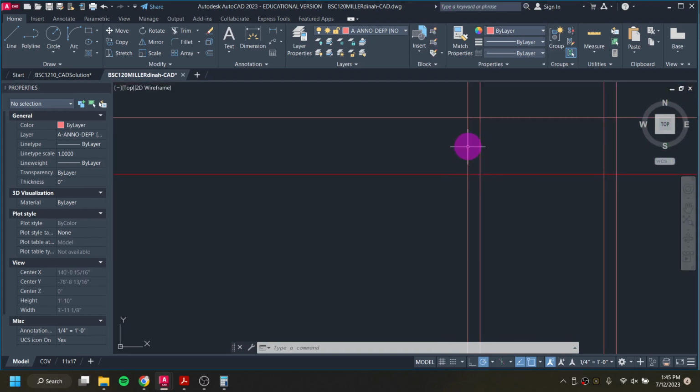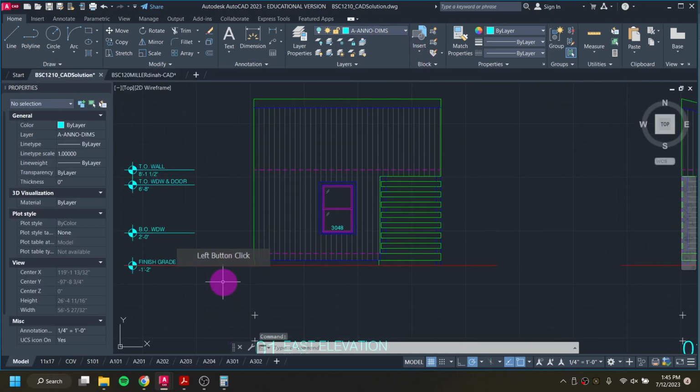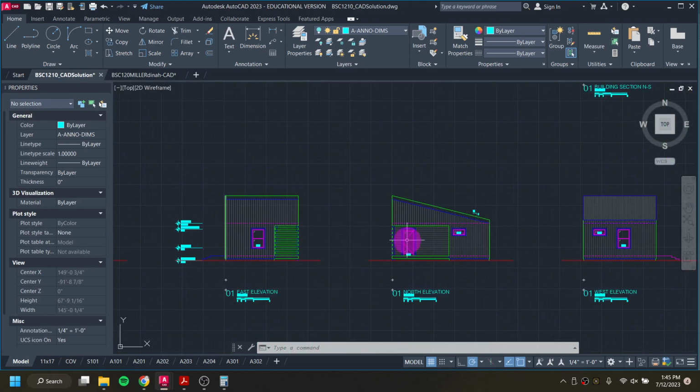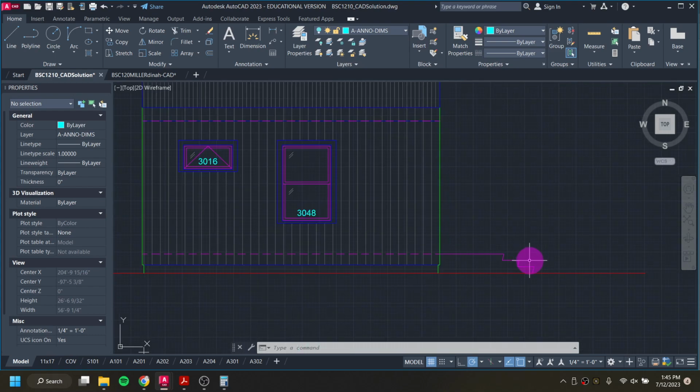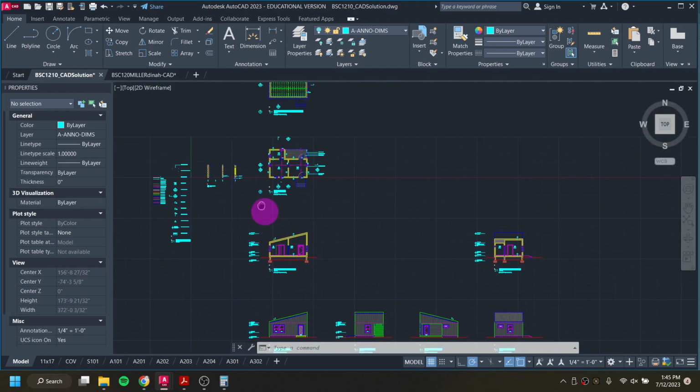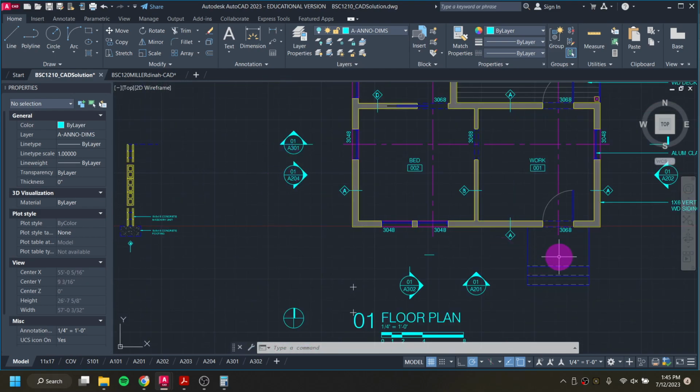So let's make sure I can do my toe height and stuff correctly. In this view, because our steps are a little bit closer to us, the viewer, the steps are drawn blue. If you do the optional west view, you'll see they're magenta. So this way they would print lighter, because if we're looking at the west side of the building, the steps are quite a bit further away from what we're looking at.